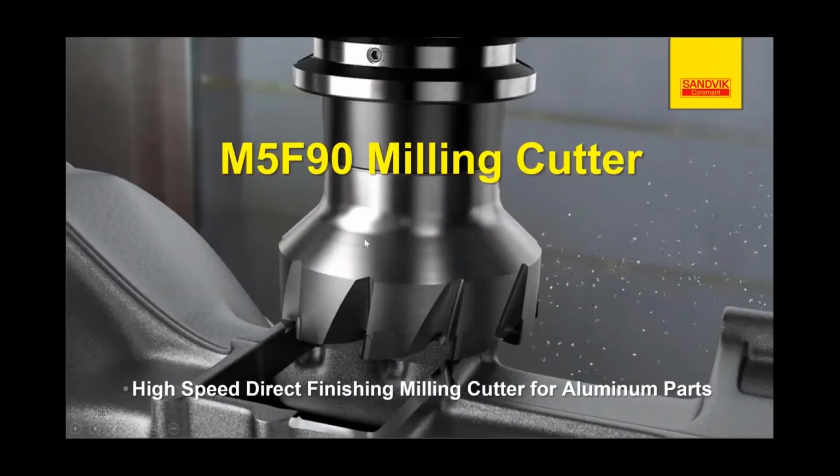What evolved out of the M5C90 is one we call the F90, and this one has brazed inserts in it. This thing's got these PCD brazed blades that are finished with a laser. And that's how we get the accuracy and the consistency and the perfect edge prep. You can't have a dead sharp diamond insert. A lot of people think they are, but no, you have to have a very, very slight hone on it just to keep the edge from fracturing. And that's what we do with a laser. The final cutting is done with a laser.